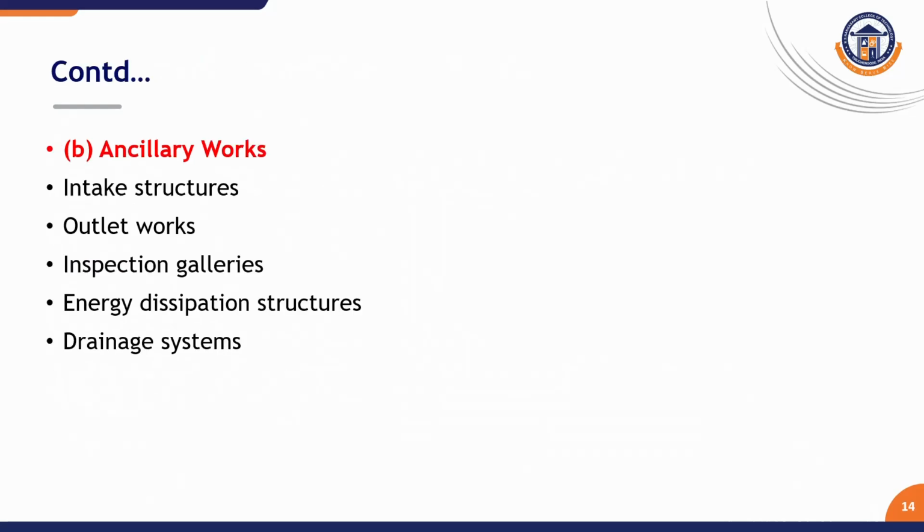The second one is ancillary works. Ancillary works include intake structures, outlet works, inspection galleries, energy dissipation structures, and drainage systems. These components ensure safe and efficient functioning of the dam.